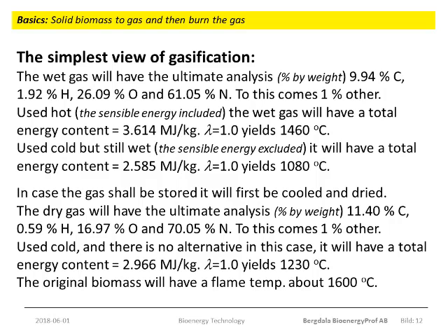So consider 4 different cases and compute the flame temperatures. The original biomass is solid, so in that case you must assume an excess air factor about 1.2. For the 3 cases with a gas fuel, you may assume the air factor at unity.